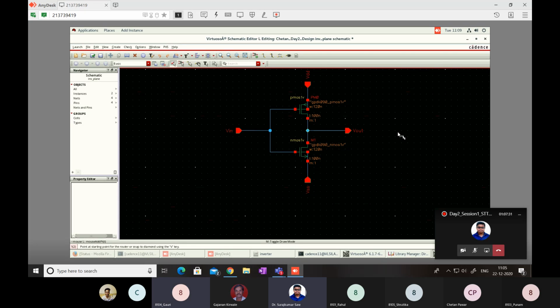Not like delay time. 40. See, take half the period, that is 50 nanoseconds. Then you have to take the average of these two, that is 10 and 10. The average of these two will again be 10 only. So the 10 will be included in the rise and fall. So the effective width will be only 40 nanoseconds, right? Okay, sir. Okay, fine. See, one I have put in, another I also have to check again.